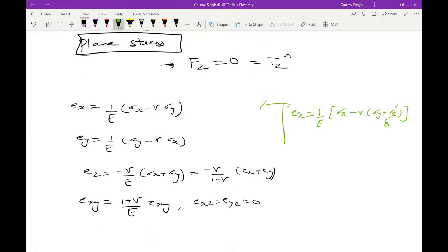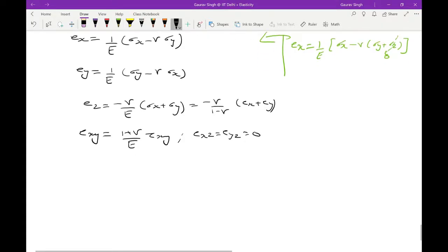So then you will get this term, and similarly the other terms are also easily found out, just using this inverse Hooke's law. Like we had done before, you can write out Ez as you see in terms of Ex and Ey. So if you find Ex and Ey at any point, you can just find Ez, so you don't have to separately find it.